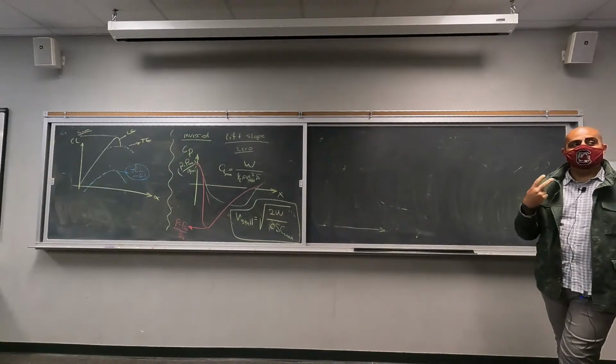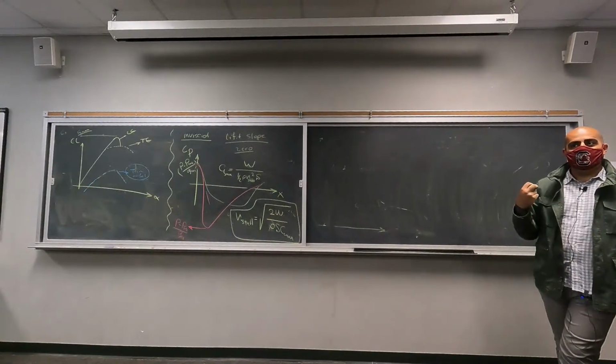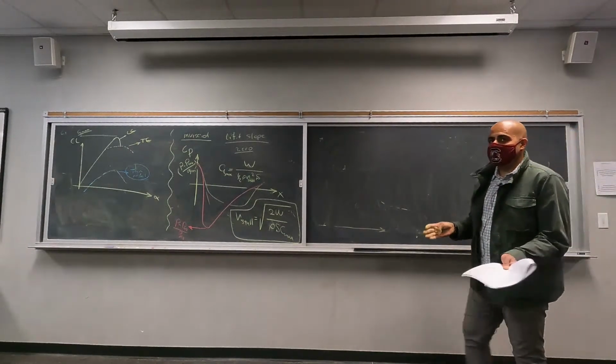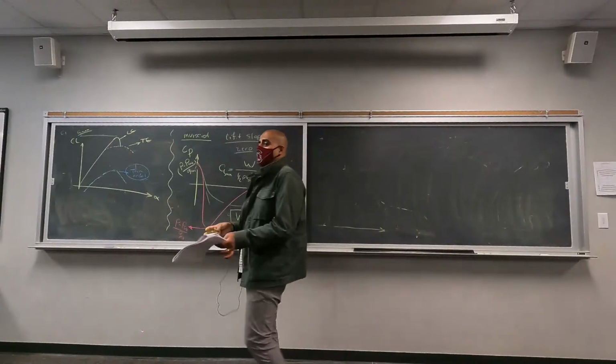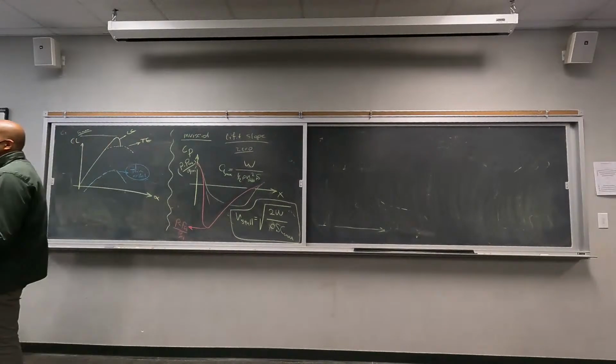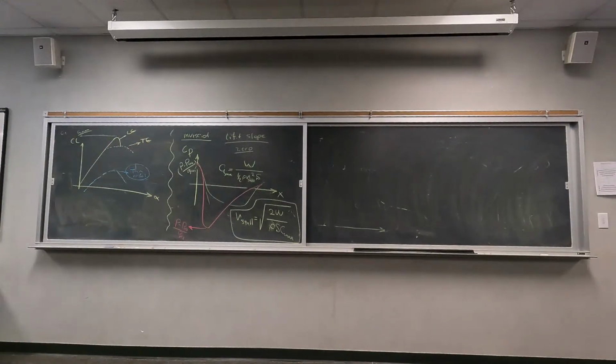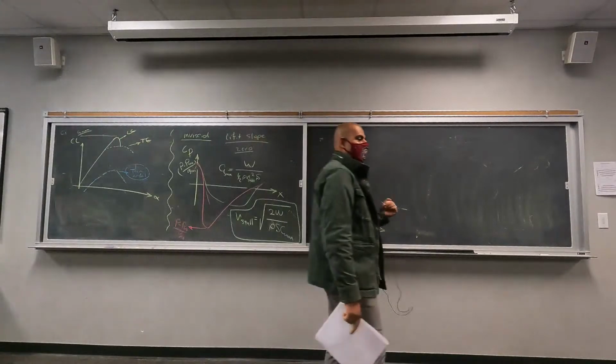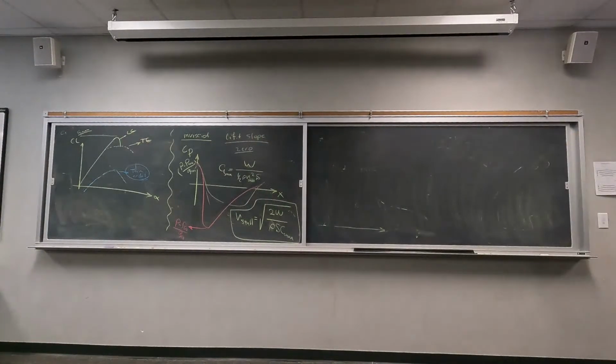So what were the two different types of airfoil we analyzed? We divided our analysis to two different types of airfoil: symmetrical airfoil and cambered airfoil, right? Cambered airfoil is going to give you negative zero lift angle of attack, right? And also higher lift coefficient. That was the idea of the cambered airfoil. So one mechanism to increase the maximum lift coefficient you are going to get out of your system is to increase the camber, right? So there are two goals here.